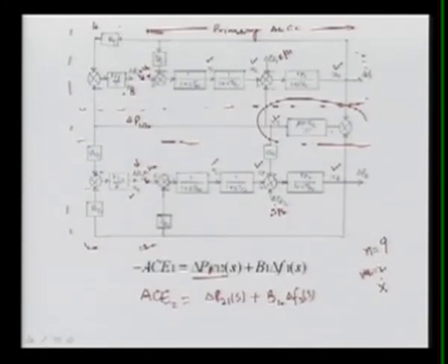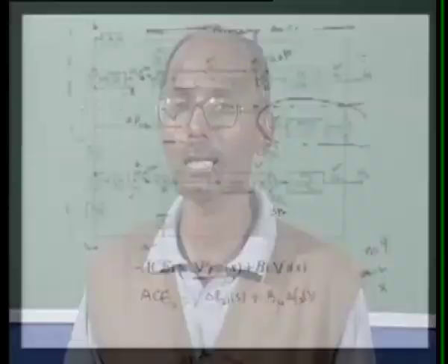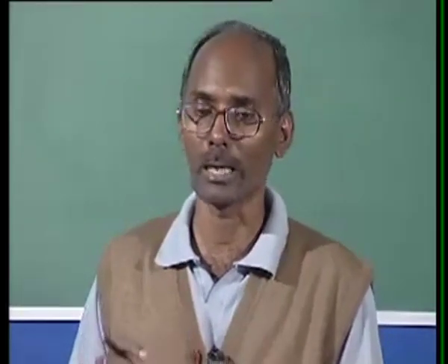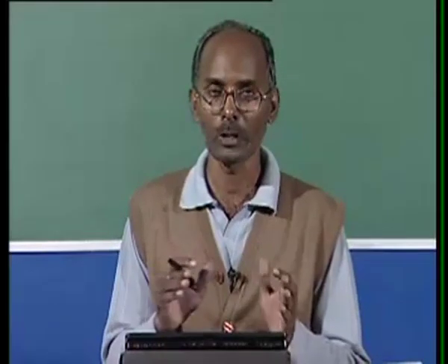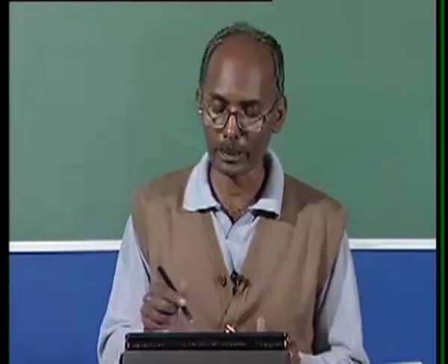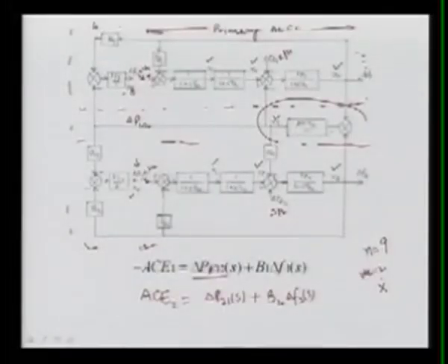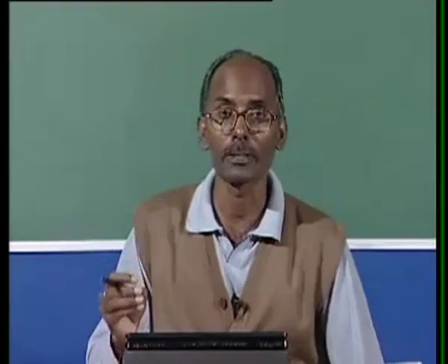Here the main objective is why we are trying to do that. Normally for the optimal control, the inputs U1 and U2 are created by a linear combination of all the states, means that is a full feedback. Here we are taking only one state. But in the optimal control design, we have to take the linear combination of all the states, starting from x1, x2, x3, x4, x5, x6, x7, x8 and x9.